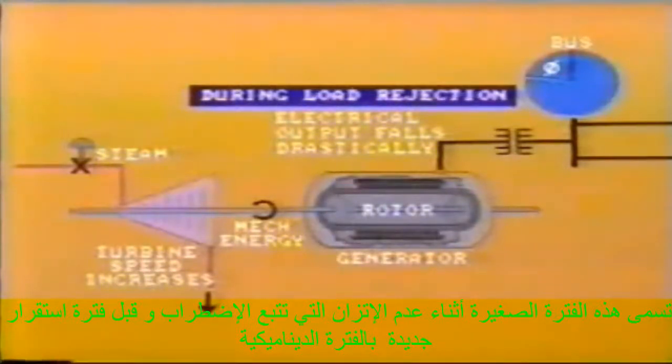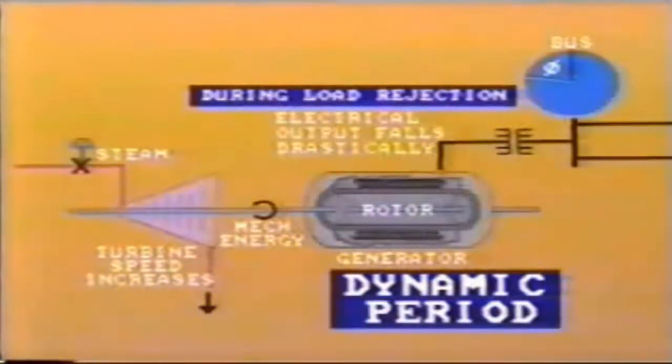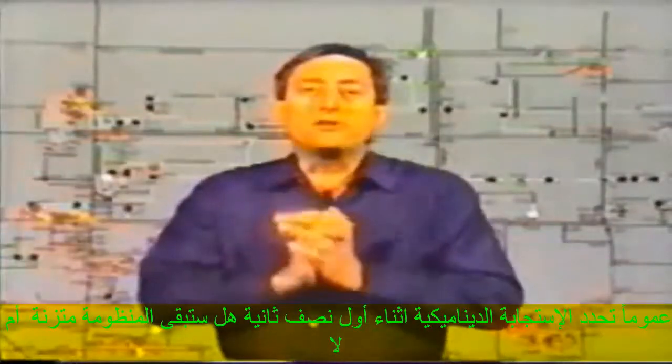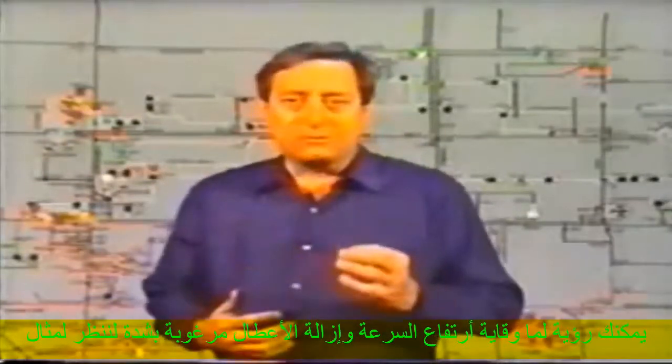This short period of time during imbalance, immediately following the disturbance and before a new steady-state condition is arrived at, is known as the dynamic period. The dynamic response during the first half second generally determines if the system will remain stable or not. You can see now why high-speed protection and removal of faults from the system is highly desirable. Let's look at a few examples.